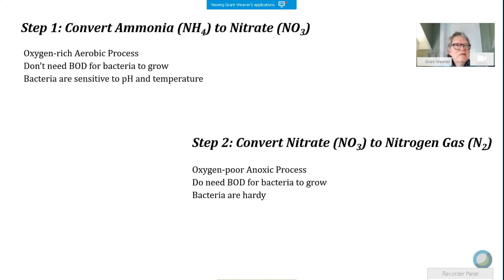So that's always a risk if you're tinkering with the process, and this is probably not the best time of year to start. It's best to start in a couple months from now when the water warms up a bit. pH is very critical, but pH down to about 6.5 typically is good enough. If it's more acidic than 6.5, that's where ammonia removal becomes a problem.